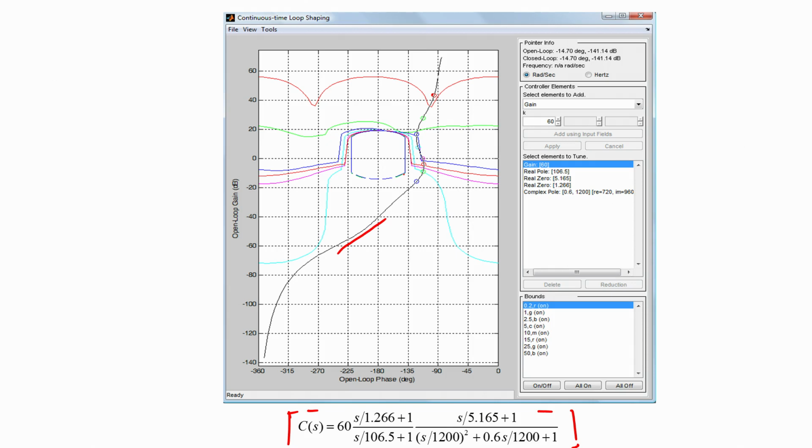Since it is not touching but it is actually avoiding the forbidden circle, namely this stability bound, by a certain distance, the maximum value of the transmission function T1 for the worst case combination of the plant's gain and pole locations will be actually less than 3.5 dB. So we have therefore now designed a closed loop system that is actually somewhat conservative, because at each of the frequencies the loop gains are well within the bounds that have been specified.